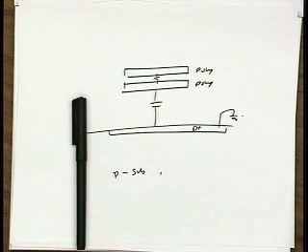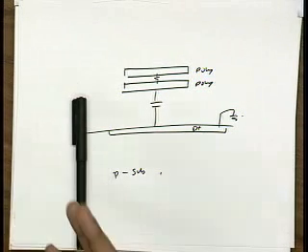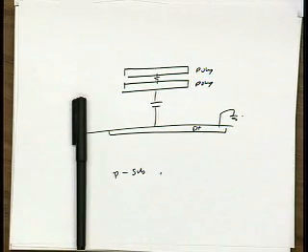Nowadays, actually, most processes have an option of giving you a high-quality capacitor. So, in particular, we'll look at a process that gives you a MIM capacitor, not even poly, MIM, which is even better in the sense that the plate resistance is going to be much lower. And those are not sitting right on top of the substrate. In fact, they're up at really high metal layers, so they have very low backplate parasitics. Okay.